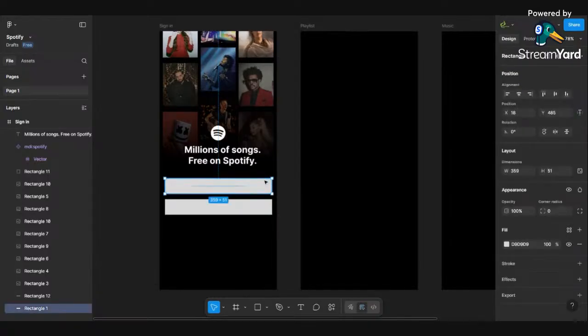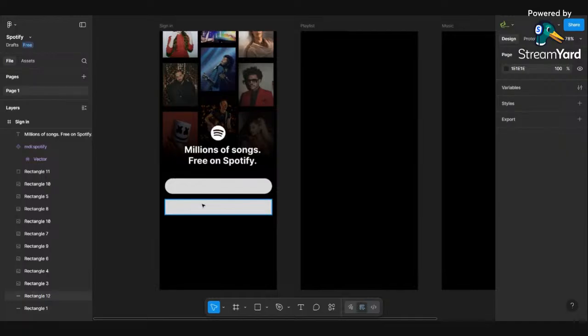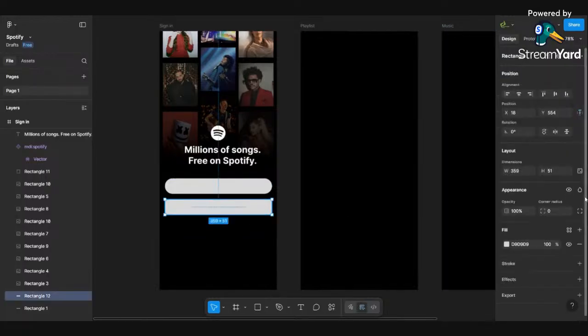As you can see, the corner is rounded, right? So after clicking it, in the same toolbar over here in the appearance section, there will be corner radius. You can type anything here or click on it and drag sideways so you can actually see to what extent you need. Yeah. So the corner is 30. I think it's pretty fine. So for the others also it must be 30. So I'll be doing the 30 for the others also.